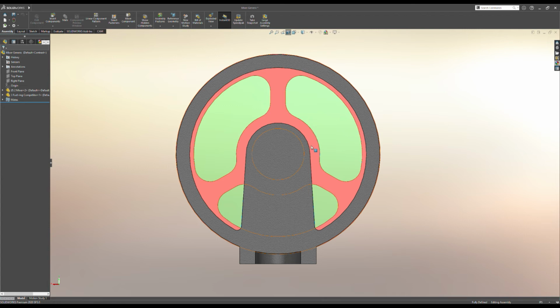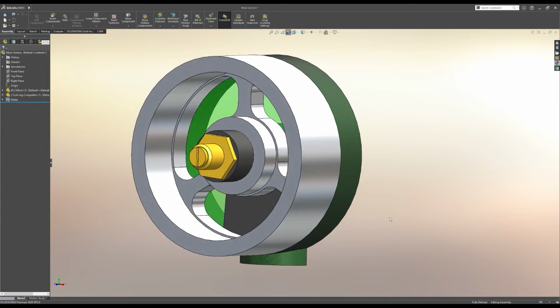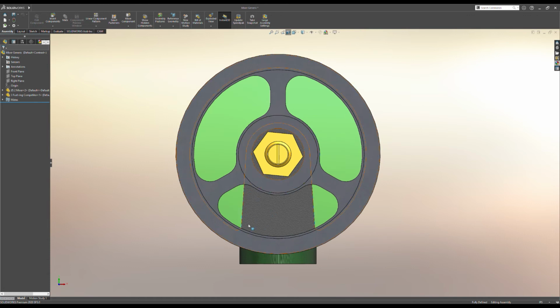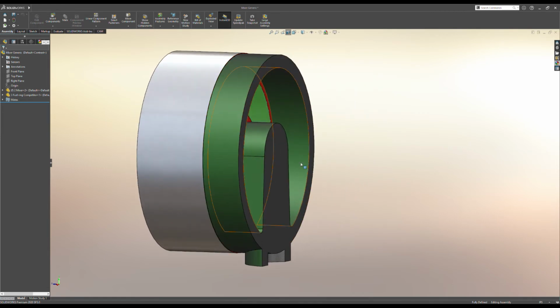So as you can see here, there's quite a bit of material that is restricting airflow. We have a decent amount of air that's able to flow through these green sections. But the mixer body itself has this large cavity where there's no support for the fuel ring. So we have all this area here that we could use to improve the fuel ring design, and that's what we wanted to improve on with our design.